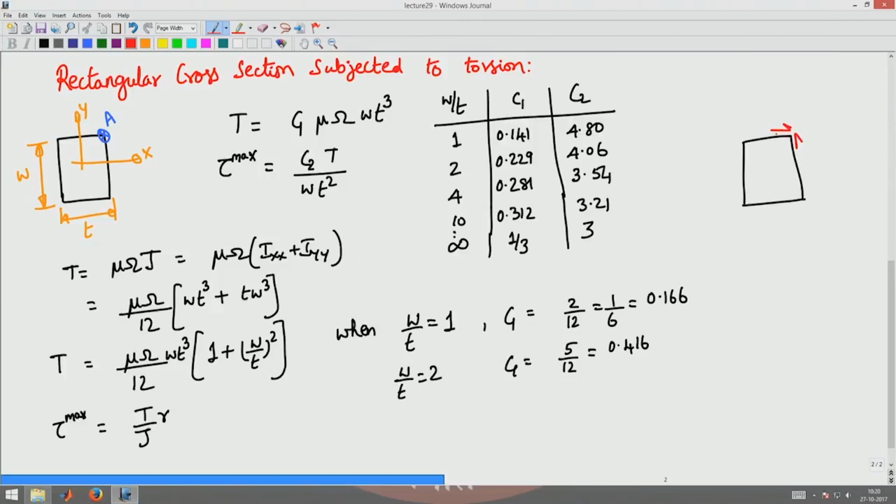If I take a section here and look at this sectioned element, there is no complementary shear coming here, this shear is not there. So, there cannot be this shear too. This shear is not there, so this shear also cannot be there. That is why the shear stress at point A has to be 0, which will be satisfied when you have warping of the cross section, and hence the torque required to engender a given angle of twist is lesser when the section warps.